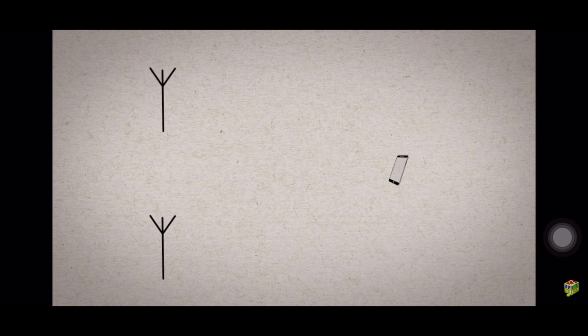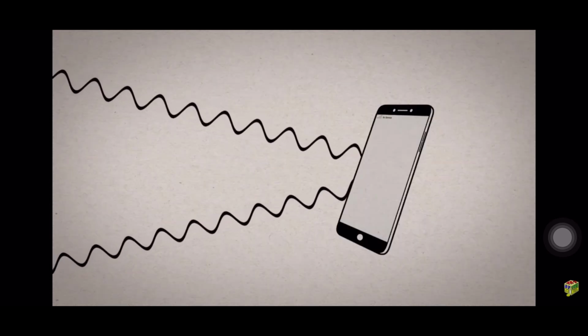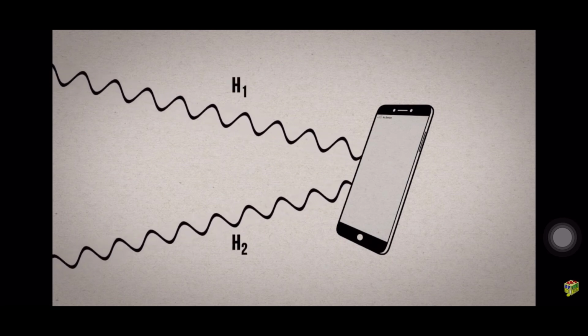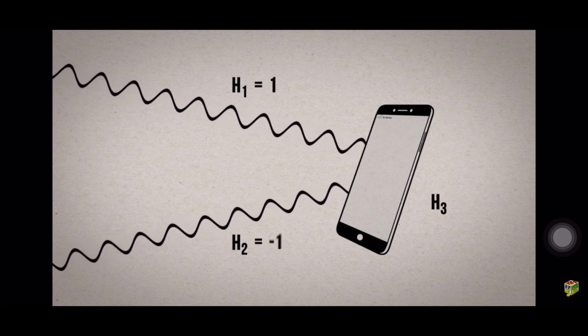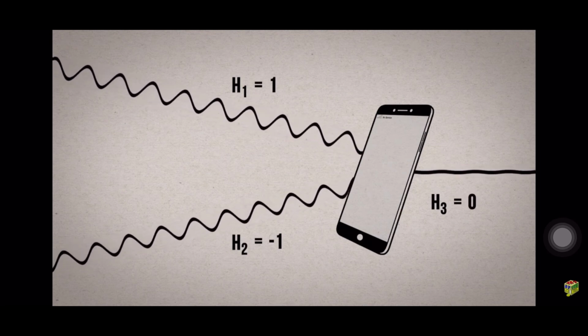For example, using a second transmit antenna separated by a distance, sending the same signal. As before, because these signals travel unique paths, they will fade differently, H1 and H2. And this gives us two chances to receive the signal correctly on the receiving end, with a single antenna. However, there is one subtle problem to address to make this system work. It's due to the fact that the transmitted signals will combine at the receiver antenna. So from the receiver's perspective, it looks like a single signal was received, with a new fading characteristic, let's call it H3, which is the addition of H1 and H2.